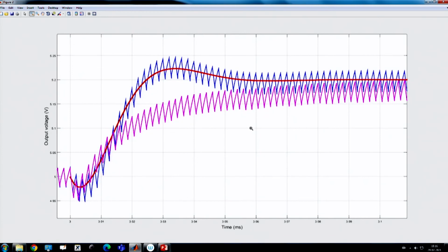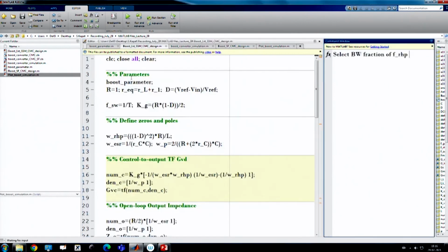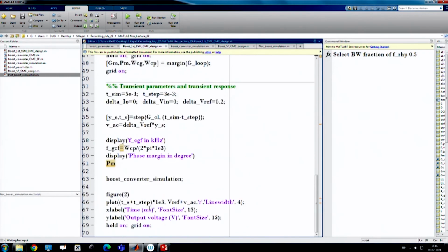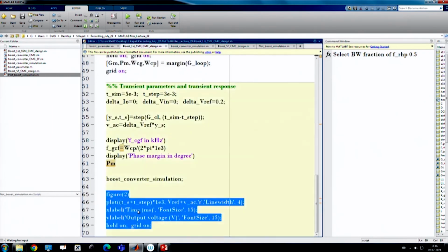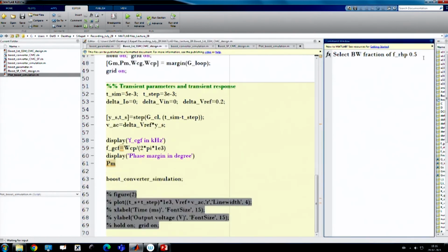I mean, it is overdamped, so you have the flexibility to increase the gain, but this has overshoot. Now, I want to increase the bandwidth of the original design, that means I want to use, let us say, 0.5, and here I do not want to use model matching, because I want to first compare the response, and the state feedback design I am using red color. So, let us go, and I am using half.